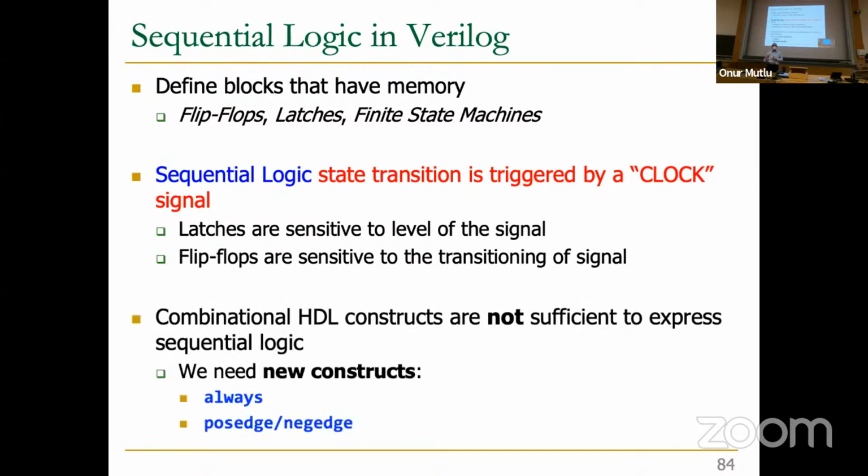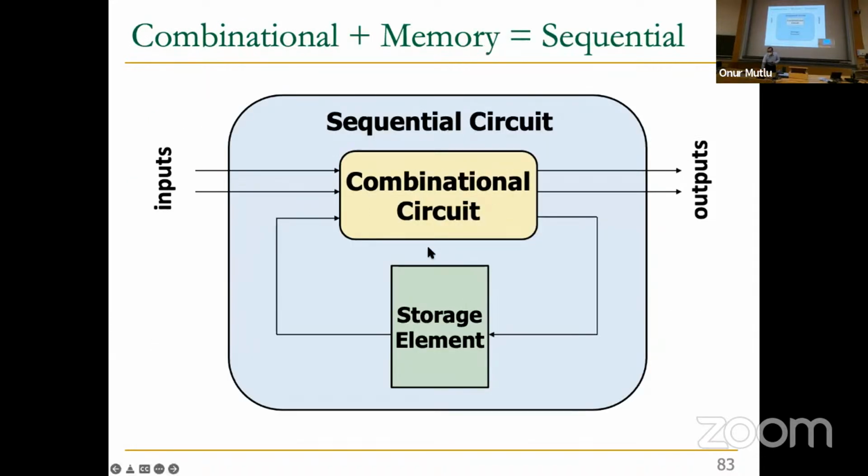And we described why this was necessary for building finite state machines, because you need to have the entire clock cycle available for the state, because that state, that value, is used in the combinational circuit over here. So as you can see, the value of the state is used in the combinational circuit along with the inputs. And the combinational circuit design assumes that the clock cycle is long enough such that the function that you implement in the combinational circuit finishes within that time before the next state is captured in the storage element. Hopefully that makes sense. This is just a summary of part of the last lecture.